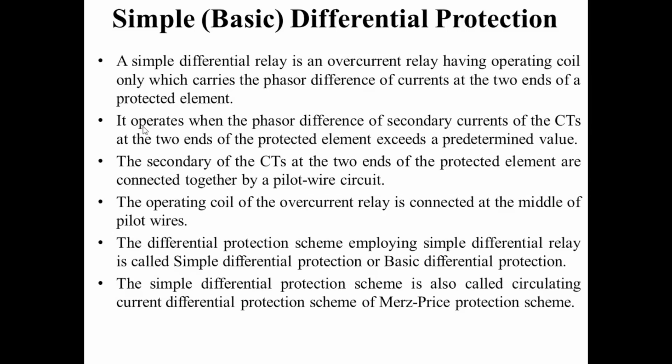It operates when the phasor difference of the secondary currents of the CTs at the two ends exceeds a predetermined value.